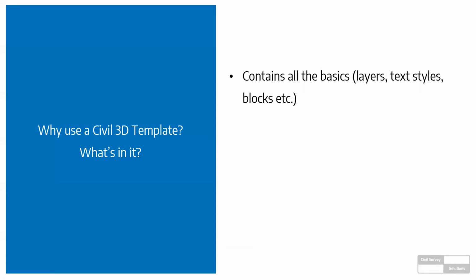So in the next hour, we're going to look at the fundamental pieces that make this up. We're going to look at these controls, and we're going to look at how we impact our Civil 3D objects with the styles and settings throughout the system. How does it work? Everything in Civil 3D is a civil engineering object. All of those objects can be displayed in a certain way and have certain parts that make up what that object looks like. You use an object style to control what you want to show for the object that you're looking at the time.